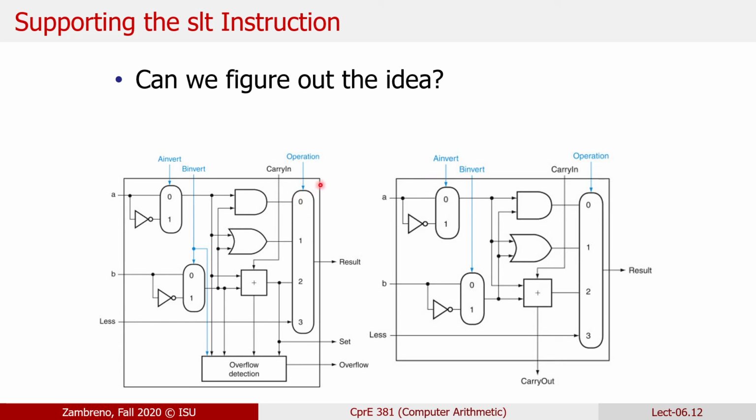Already in lab 2, for many of you, you treated the most significant bit slightly differently. You didn't have to, but many of you did. Certainly now for the project part A ALU, you definitely do have to treat that most significant bit as a slightly different component with slightly different logic going on there. And part of that would be for that set operation, and also for overflow as well.